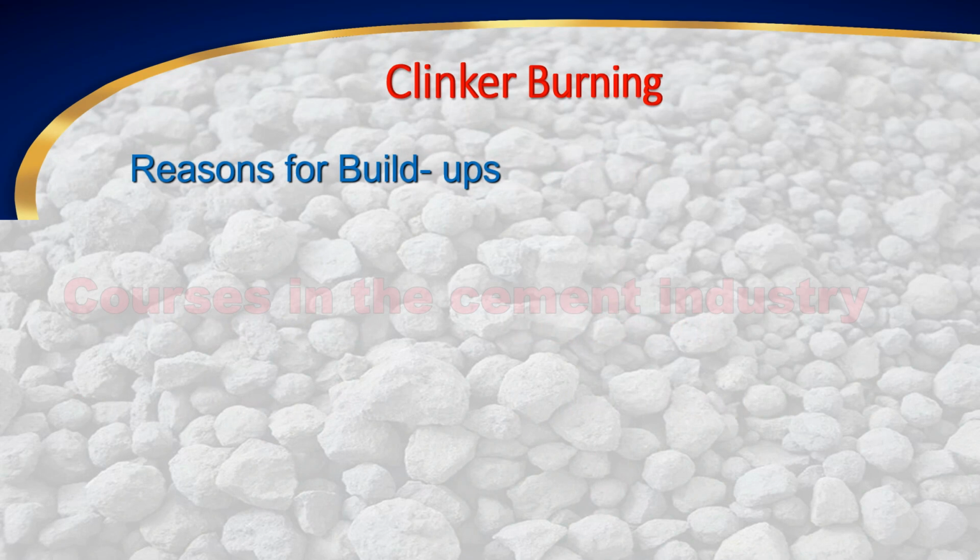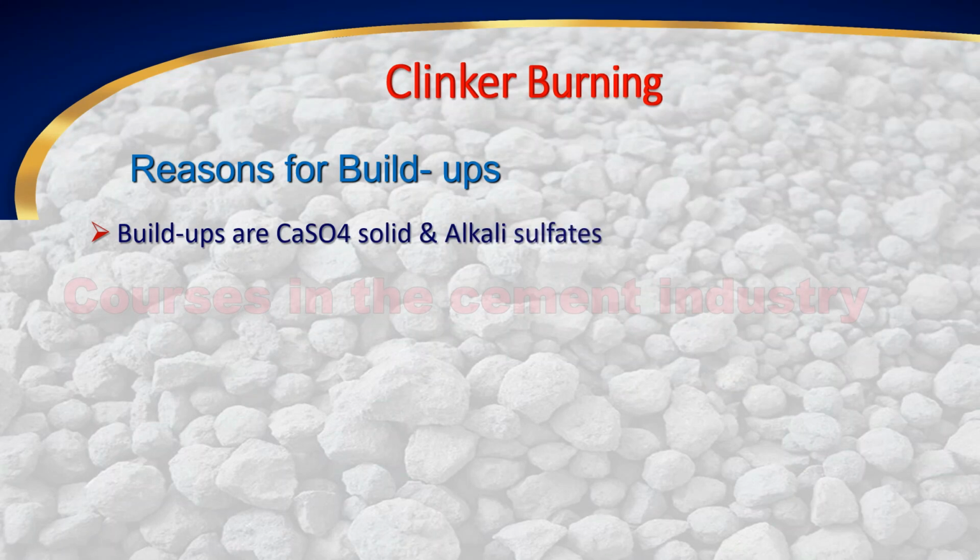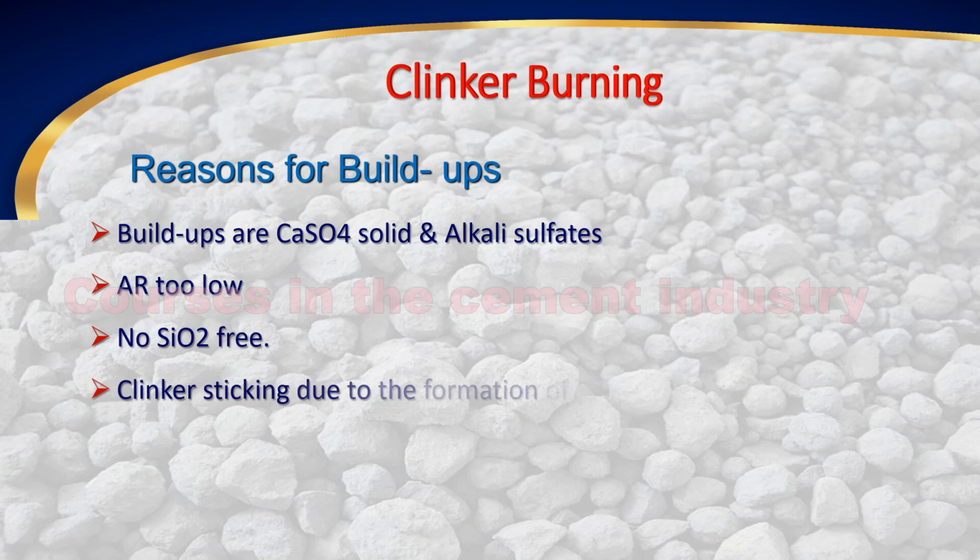Reasons for build-ups. 1. Build-ups are CaSO4 solid and alkali sulfates. 2. Alumina ratio too low. 3. No free SiO2. 4. Clinker sticking due to the formation of alkali chloride.